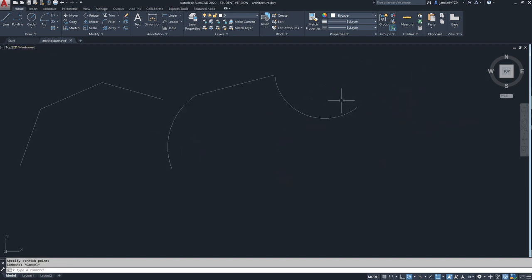This polyline command will be used a lot in the 3D world. When you create a 3D object in AutoCAD, you're going to have to use a polyline, because a 3D object consists of a single solid object, and the 2D will construct that, and that has to be a polyline. Also, if you look at this arrow button, you get to see other polyline type things, for example this Spline Fit or Spline CV.